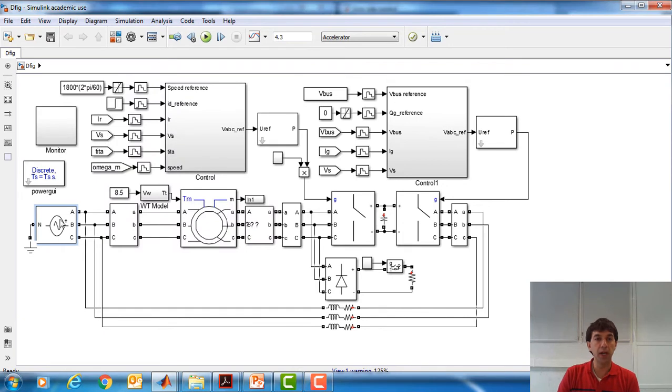Okay, so here we have a voltage dip which is asymmetric, which is unbalanced, and what we did in video tutorial 7 is, by means of the rotor side control, deal with this type of asymmetric voltage dip. And now in this video tutorial we are going to implement the required control strategy at the grid side converter in order to deal with this asymmetrical voltage dip, which is also seen by this grid side converter.